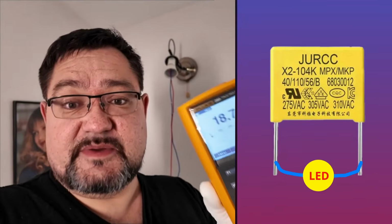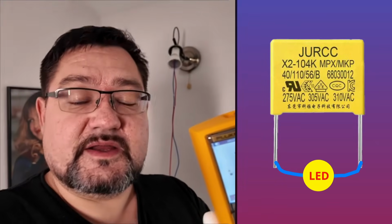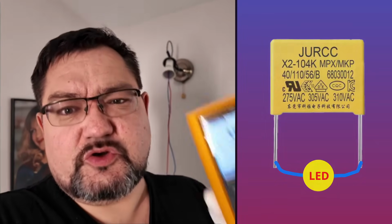And how do you deal with this? You install a special X-class capacitor in parallel with the lamp, 0.2 to 0.6 microfarads at 400 volts. The capacitor will shunt this current without drawing the current that the meter counts. By the way, any energy that comes into your house, including this phantom energy, doesn't bypass the meter, it all goes through the meter. But this phantom is parasitic energy that just seeps through the capacitance into your sockets, lamps, to the LEDs, but doesn't do any useful work. On the contrary, it only gets in the way, making your LEDs glow at night.